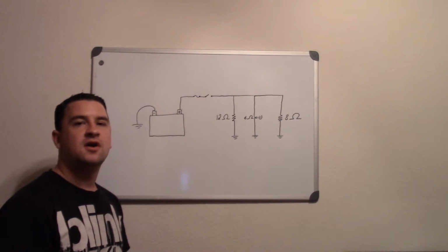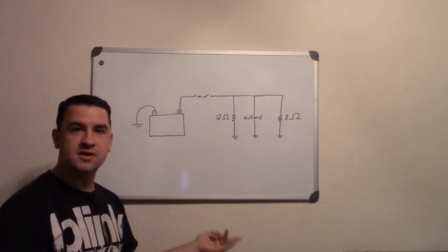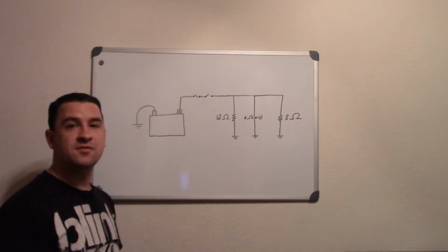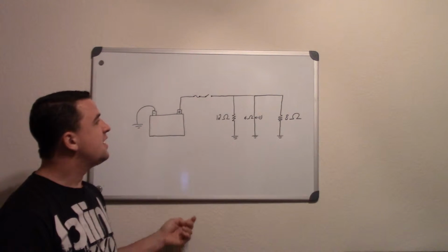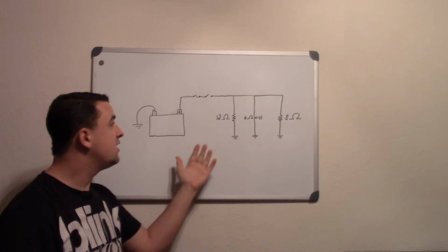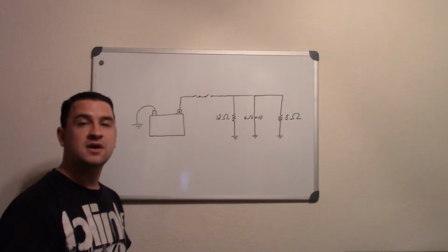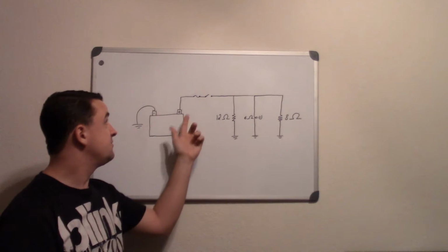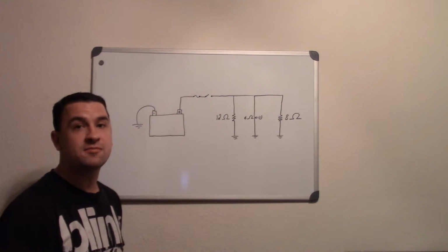Now we have our next set of circuits, which is parallel circuits. The characteristics of what goes on in them are a little different from a series circuit. What makes the difference is that instead of having only one path for your current to flow, you have multiple branches. That's what you have in a lot of automotive circuits, especially light bulbs. They may work off the same power, maybe even the same fuse or switch, but they have multiple branches, one for each bulb.